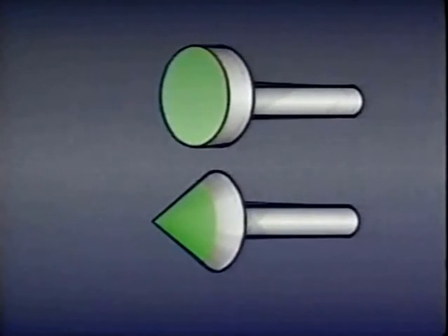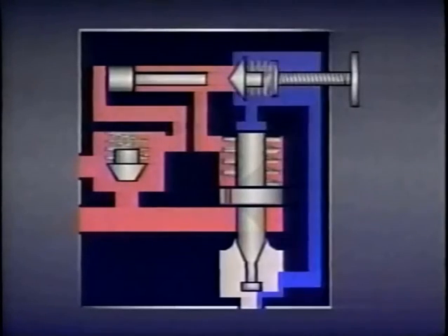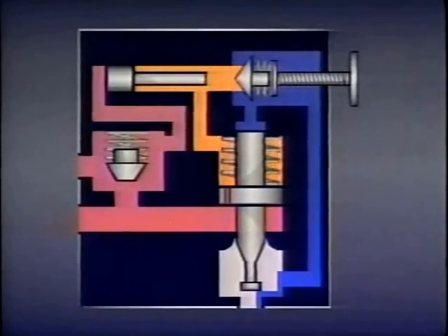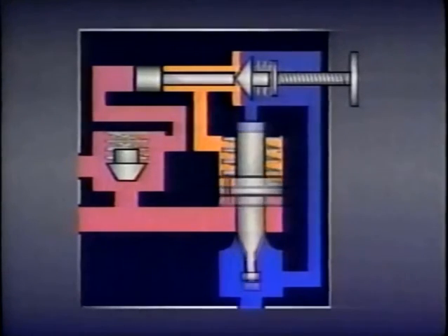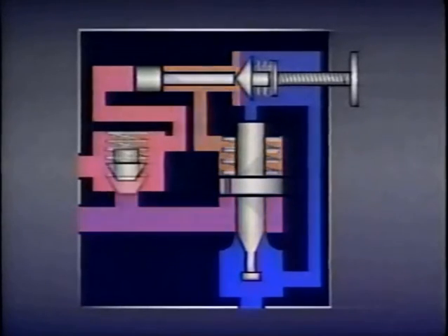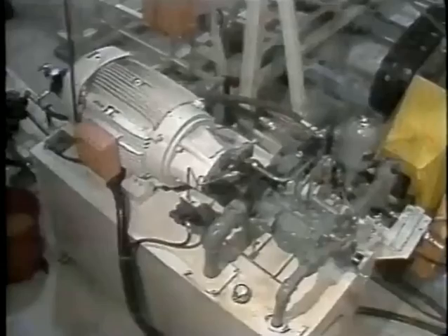The pressure differential at which the valve operates depends upon the difference between the area of the face of the piston and the area of the dart tip. Typically, the piston face is 15% larger than the dart tip. Therefore, the piston doesn't shift back until pressure on the accumulator side has dropped to 15% less than what it took to open the dart in the first place. In this way, a differential unloading relief valve allows the pump and motor to unload when an accumulator is filled, and to remain unloaded until the accumulator needs to be filled again.